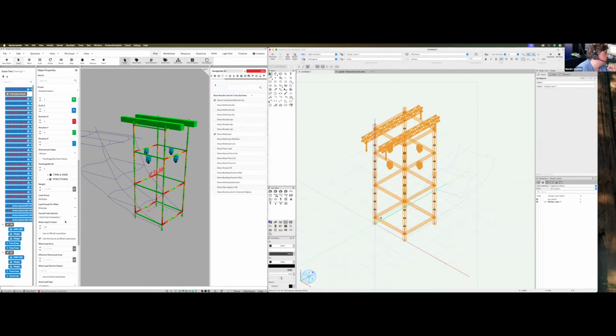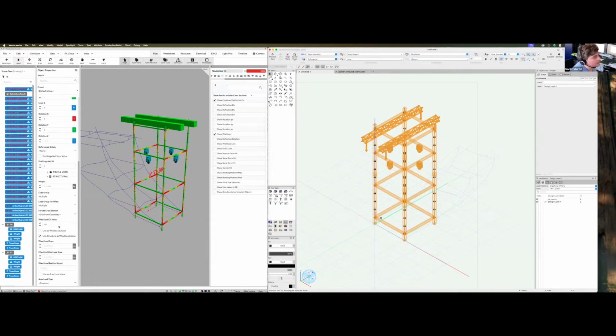For a successful calculation, you also need to update the CF factor. Look into the ground support webinar for more explanation about CF factors, but that basically defines, depending on the shape of the object, how much of the wind force actually gets transferred into real force.